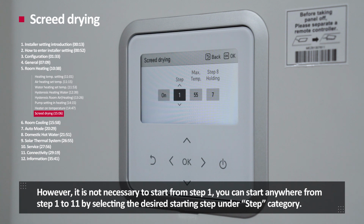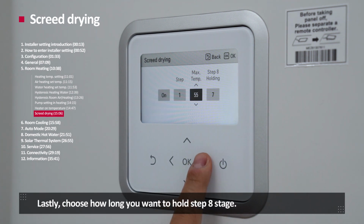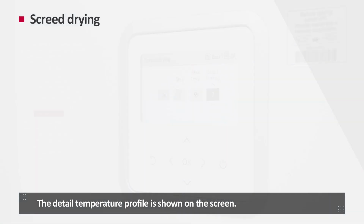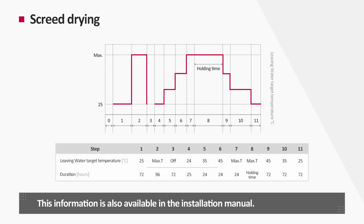You can start anywhere from step 1 to 11 by selecting the desired starting step under step category. Maximum curing temperature can be defined between 35 and 55 degrees Celsius under the max temp category. Lastly, choose how long you want to hold step 8 stage. You may hold this stage from anywhere between 1 and 30 days. The detailed temperature profile is shown on the screen. This information is also available in the installation manual.